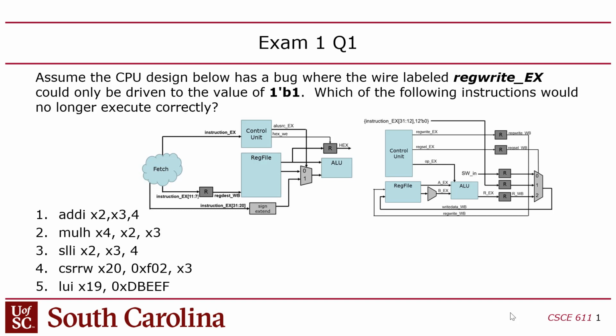Now, this is a little confusing, though, because if this were a real RISC-V processor, it would have regwrite 1 on this guy, right? But this is a hack that we use in this class for our project, where you don't want to write a register whenever the IO address for that guy is F02. Does that make sense? You guys with me?